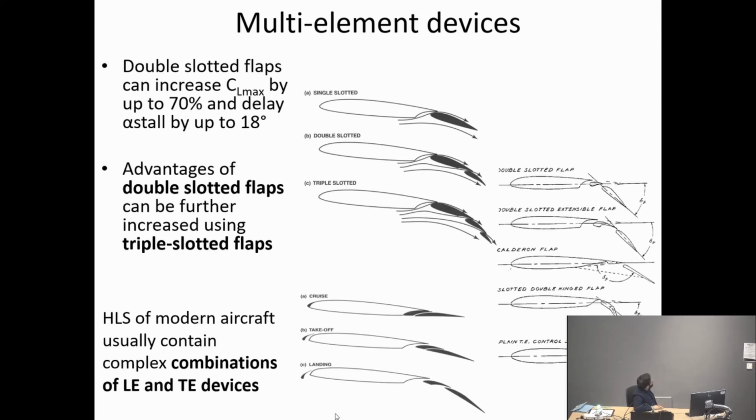okay, anyone with a hawk eye, tell me what's the difference between B and C? Very slow, landing. Fine, but in terms of just simply the operation of the devices? Less extending, yeah, very good. So here in takeoff, they're what we call partially activated, but in landing, they're fully extended. I'm not saying you're wrong, I was just asking something very particular, but this is a takeoff configuration. So partially extended, and the landing is fully extended.